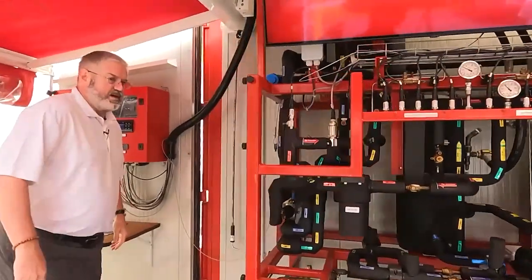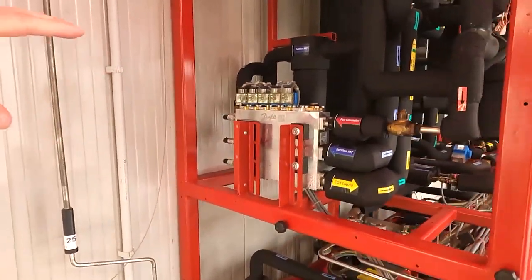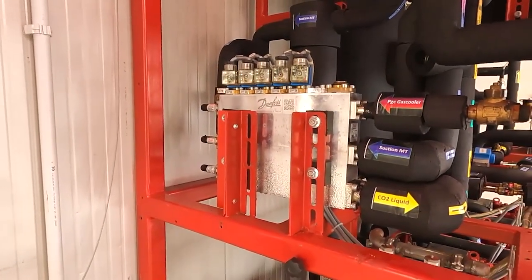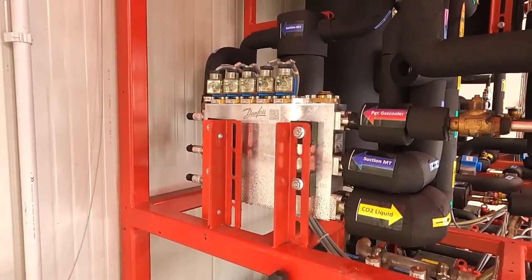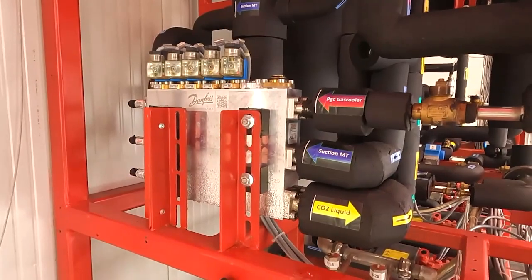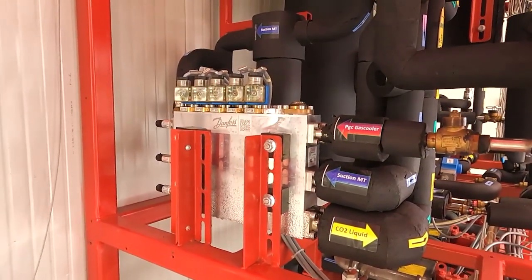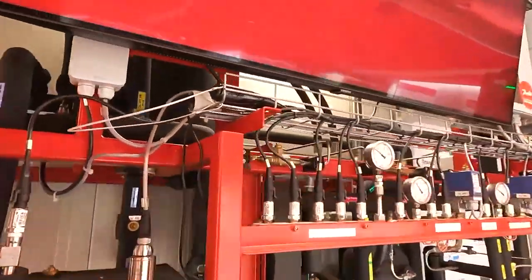So the ejector block on our system, it's over on the left side of the unit. This system was likely retrofitted with it, and that was the best place for it. But this is our ejector block here, and it is between the gas cooler and the entry into the flash tank. And then in parallel with this is our high pressure valve up here. We come around the front here. This is our high pressure valve.